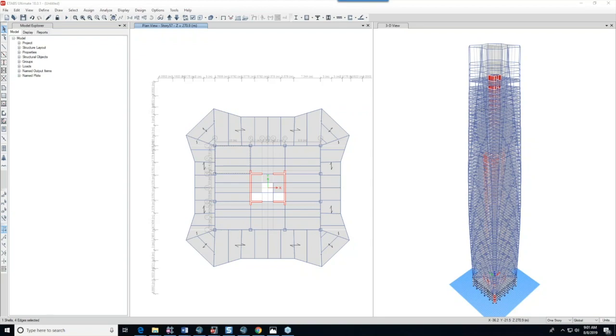There are other times when a rigid diaphragm approach would not be appropriate, and you'd want to model the diaphragms as semi-rigid. So we're going to spend some time in our webinar today exploring which of those two options is most suitable for a number of general types of conditions.